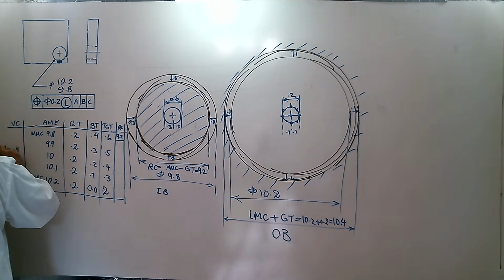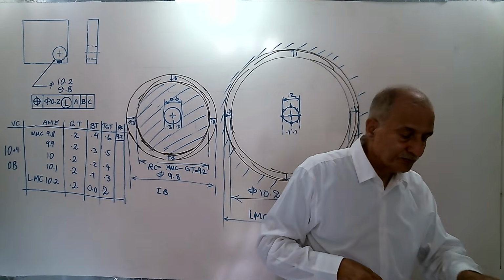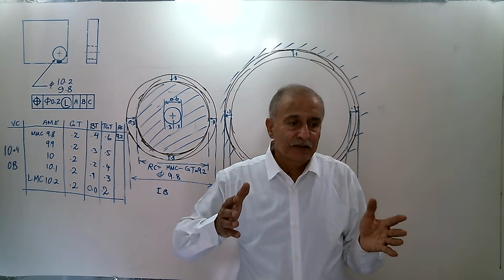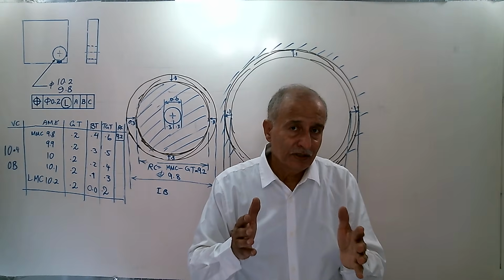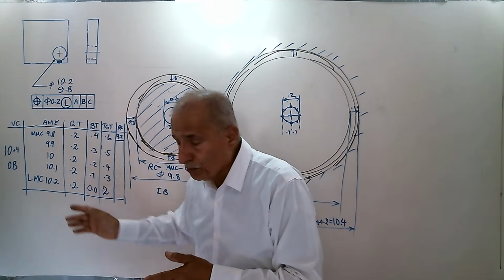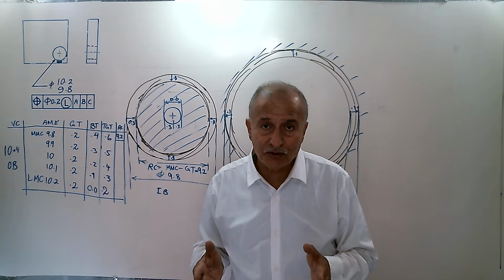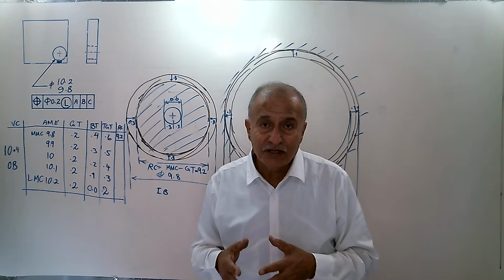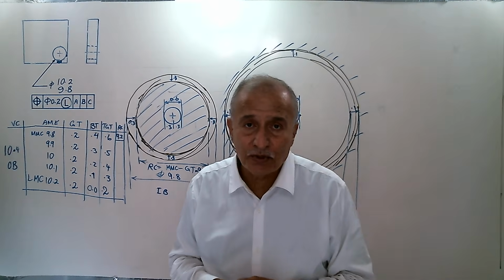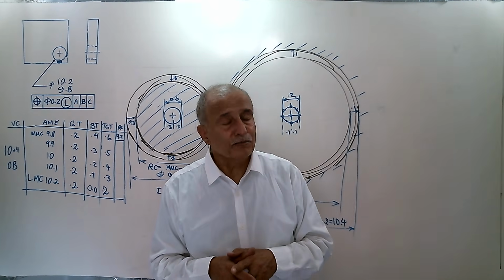let's clarify this. If I am close to the edge of the part and make it 10.2, that's the worst case scenario. This is here, worst case scenario for the designer, because the goal was material sufficiency. That's the difference between RFS, MMC, and LMC.